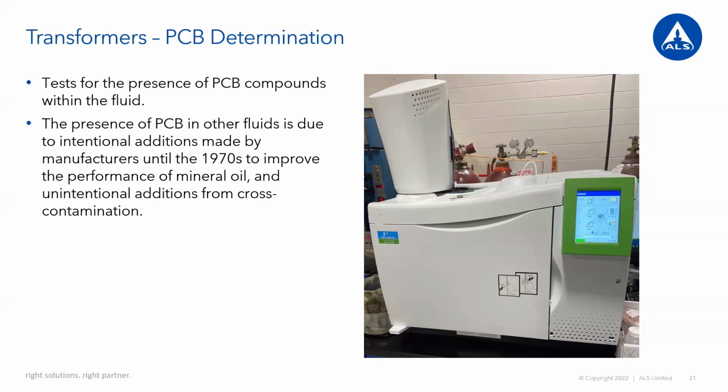Before they understood what cross-contamination was, like you have to drain down a PCB-filled transformer to replace some gaskets because they're starting to leak, and pump it back in. Then you go to the next one, you don't flush, you don't clean out, and that's just cross-contamination.